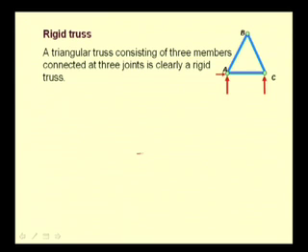If we consider any two dimensional element which is not constrained, it has 3 degrees of freedom in this plane, that is, it can translate in the x direction and in the y direction, and it can rotate about the z axis.